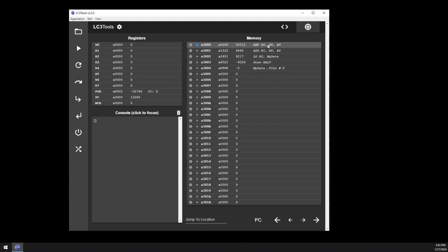Registers are used during the execution, kind of like variables, but they're like hardware storage areas that the program is going to be using. You see that this instruction has a reference to an R0, R0. This one's R1 and R0. Here's an R2. That is referencing these general purpose registers for use in whatever these instructions are supposed to do.